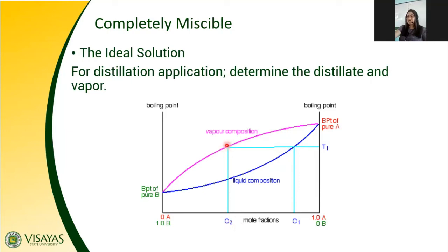So this point here represents where the first vapor phase exists in that particular system, at this composition. They have the same temperature, but different compositions of the two components, so they have different points for the first liquid phase and for the first vapor phase.